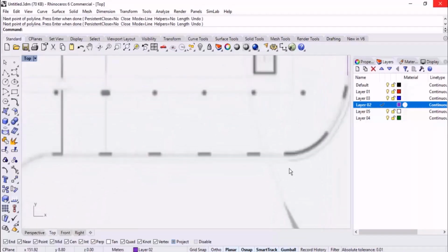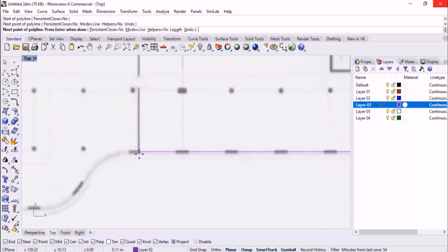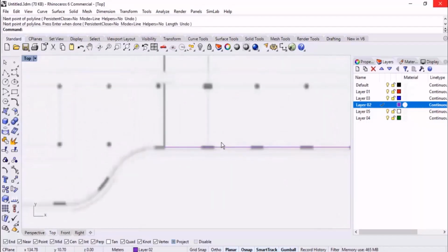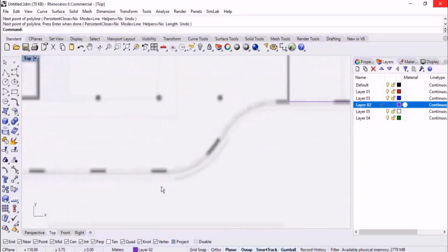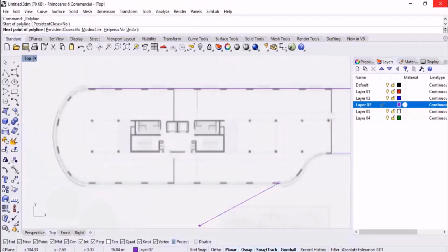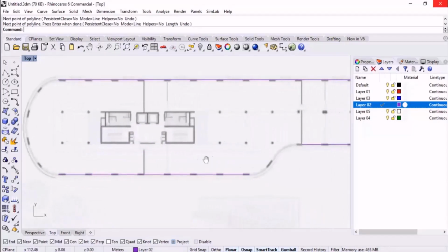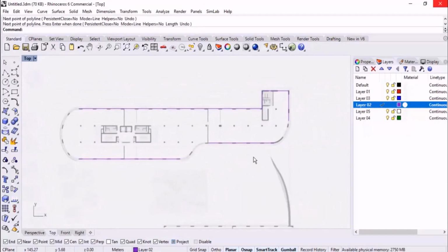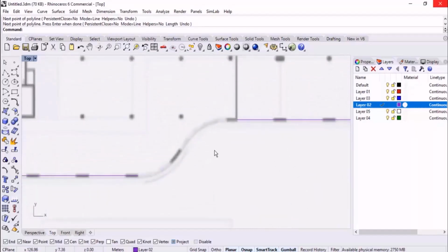I continue till here, then the other straight lines. Check this out. However, we should exceed it or extend it actually. I want to teach you how to detect clashes here. I sketch other lines. I enable the smart track, since I need parallel lines this way. Well done. But for sketching the blend, the curve, as you're concerned, we should use blend CRV.